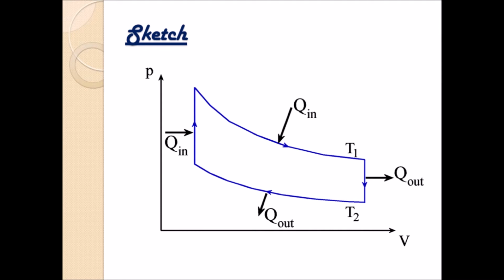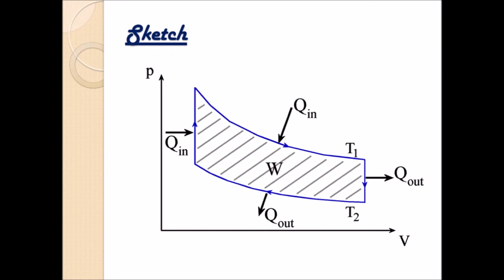And this is not all that we can take out of this diagram. Of course, this is just a sketch, so the values that are given here are not real. But what we know is that when we go around this blue curve, the area under the curve is always the work. So for region 1, yes, there is a very distinct area between the blue curve and the horizontal V-axis. And also for the third regime, where we are at temperature T2, there is a very distinct area. On the other hand, for the two isochoric processes, there is no area at all. So they do not contribute. But you can still calculate the total work that you get out of the process, which is the gray area that is indicated right here. But of course, this isn't even asked. So this is additional information.